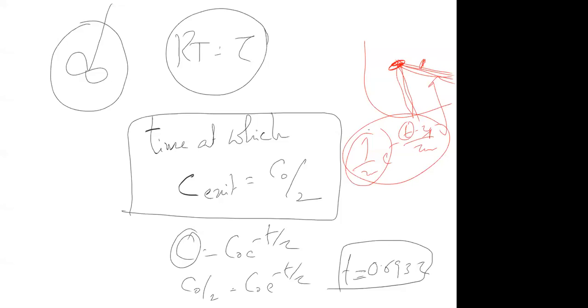In recycle RTD, the height of the peak decreases after every pass, because it decreases, no? First 100 you are sending, out of 120 going. First 20 will come, then next 80 will come. 20 means 20% of 100. Next 20% of 80 will be 16. What is left? 64. 20% of 64, which is 13. Then what is left? 51. 20% of 51, something like that.